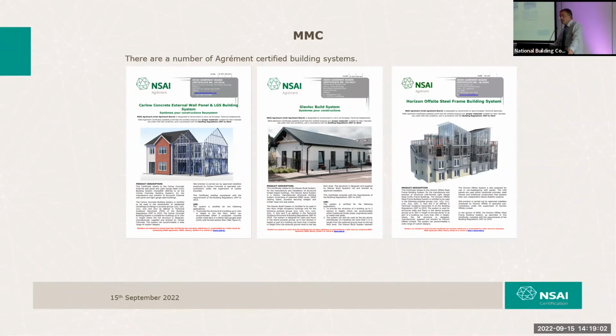So for anybody to give me a Psi value without a fully detailed junction explaining how that building junction goes together is wasting our time, okay? So first and foremost, that is what I look for when I'm performing an annual audit of a thermal modeler. Show me the detail is the first question I ask. And if they can't show me a detail, I say, well, then that's it. That's a non-conformance and a fail.